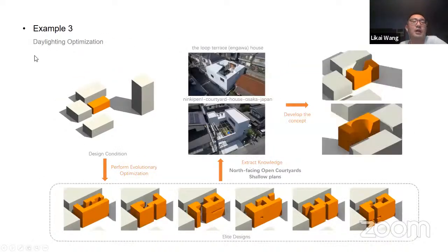And the last one is where I use daylighting optimization for the design, and then you can see that the broken boundary is missing, and all the courtyards go to the central and northern part of the design, because when we try to maximize the daylighting, we need to enlarge the space between the target building and the buildings surrounding it.